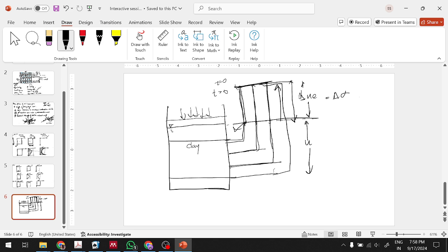And for t greater than 0, what will happen is that these boundary piezometers will go down and you will have piezometric line like this. So this will be the isochrone at any time, the path followed by the heights of piezometers attached to this sample at any given time. That is the concept of consolidation.